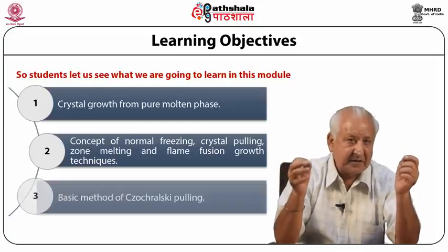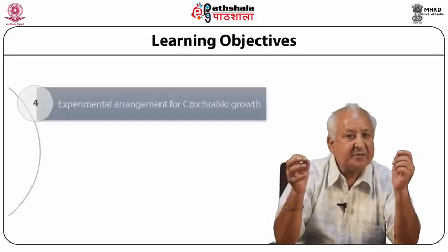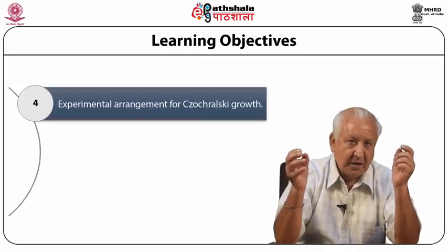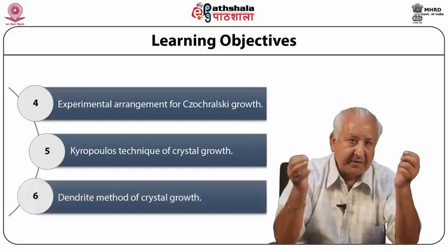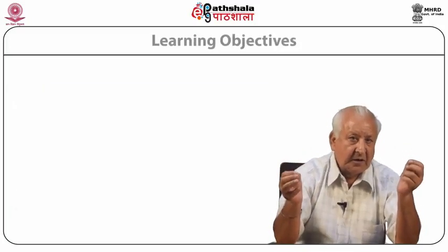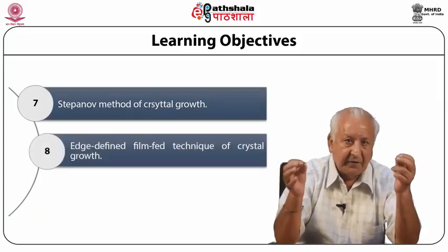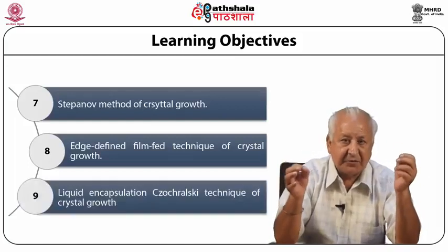We will discuss the basic method of Czochralski pulling and the experimental arrangement for Czochralski growth, the Kyropoulos technique of crystal growth, the dendrite method of crystal growth, the Stepanov method of crystal growth, film-fed techniques of crystal growth, and the liquid encapsulation Czochralski technique of crystal growth.